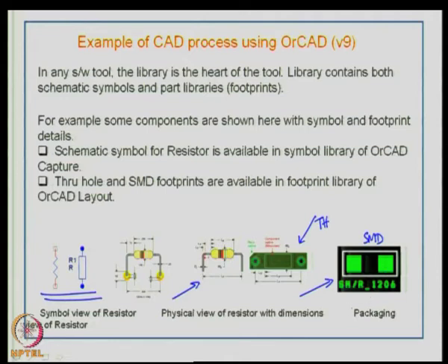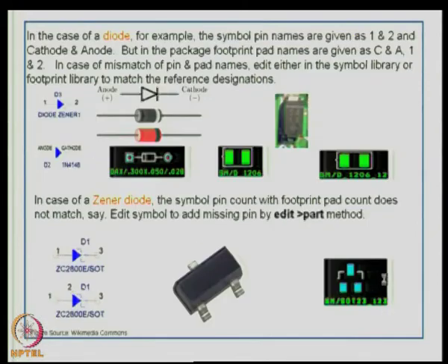So, if you look at this picture here, basically you will see pin number 1 and pin number 2 of the two resistors, and you can see the white area, which is basically telling you that is the maximum body area of the package, and obviously you can't do routing in those areas. So, that is like a keep off distance, and you can see dimensional details. So, this 1206 has a meaning, it basically indicates the size of the resistor package. So, we will see that shortly. So, these are the kind of information that you will get from a footprint library.